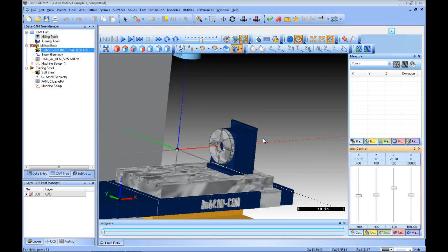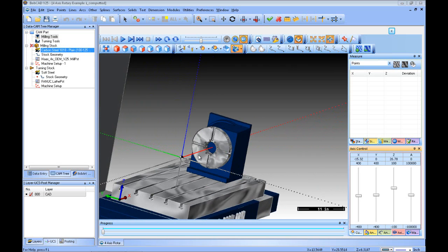Then the last travel distance you need to know is the rotation. A lot of indexers have a limit on how far they can spin positive and negative. For our example, we're going to use positive 9,999.999 degrees and negative the same before it has to lift the head and rewind the indexer back to the 0 position.